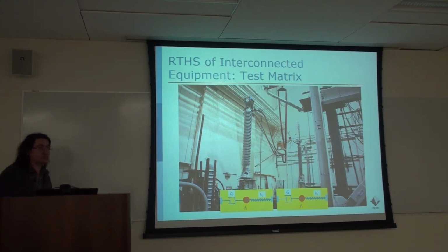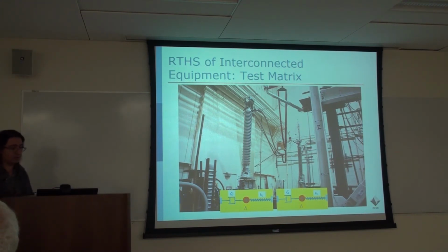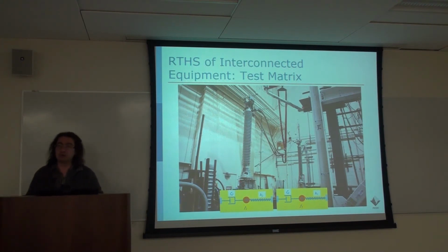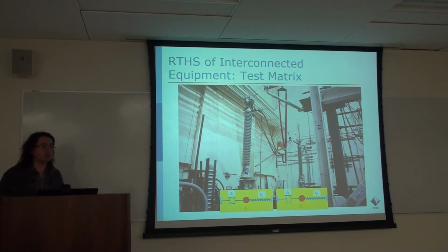And compared to the previous case that I've shown, which had the 3D analytical substructure to do the parametric study faster, we just had a spring mass damper system to represent the support structures for this case. And then, as Andreas mentioned, this becomes really convenient to do parametric studies because you can easily change the support structure condition and run it and finish the whole thing in one day or in one afternoon or one night, whatever.